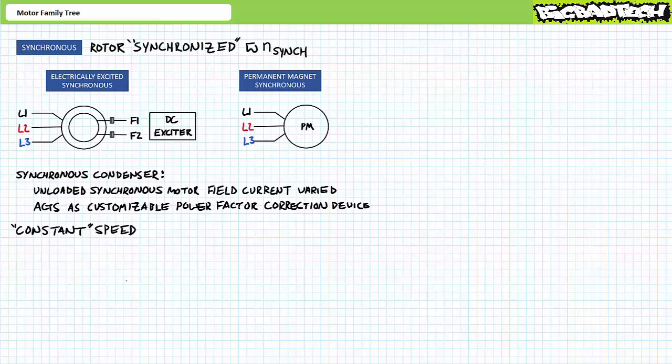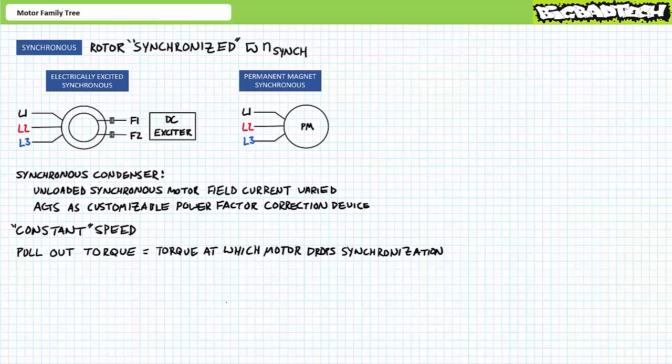Theoretically, synchronous motors, regardless of construction, can be expected to maintain synchronous speed regardless of applied load inside their operational range. These devices are not magic though, and they do have practical limits outside of which they cannot perform as advertised. Pull-out torque is the point at which a synchronous motor is so loaded that it pulls out of synchronization. You'll immediately be aware of this event because of the change in speed, torque, and electrical characteristics, horrendous noise, and your lab instructor's boot planted firmly in your butt telling you to shut her down.